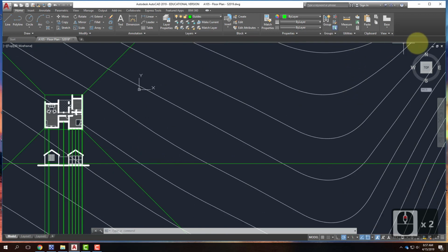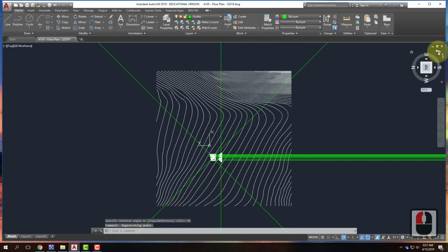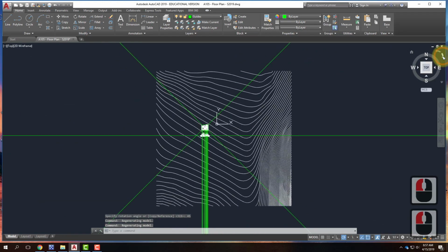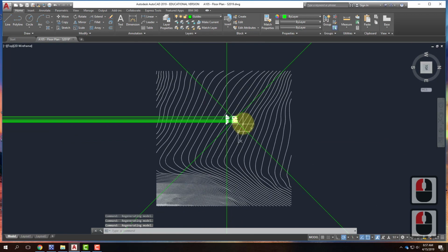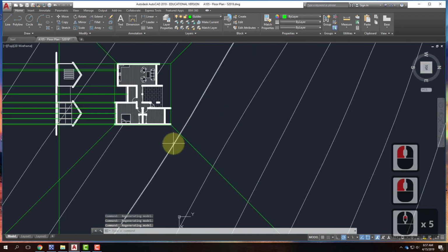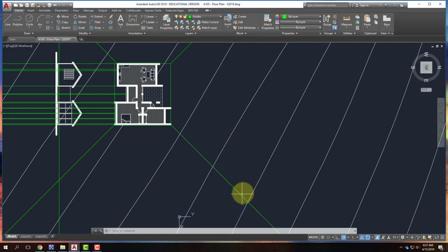However, a lot of you struggle with seeing it. So there is a trick built into AutoCAD. If I come over here to the little compass, there are these arrows up by where you close the drawing. And if you click on one of those arrows, it will actually, sorry, wrong direction. It will rotate the view for you. So you can now look at it and pull your line straight down again. So it makes life a little bit easier.